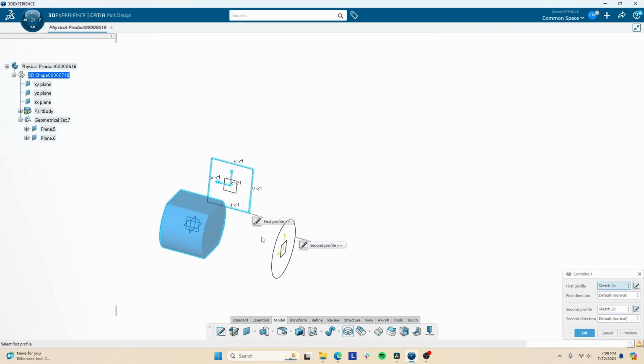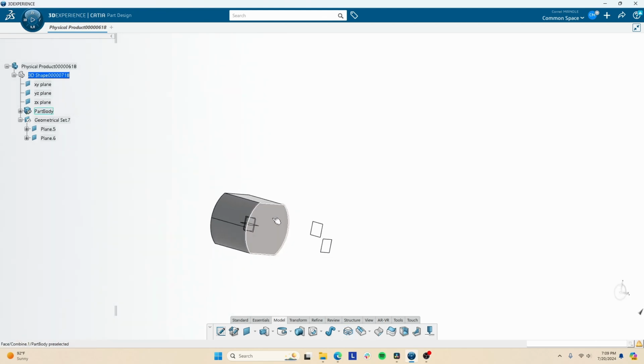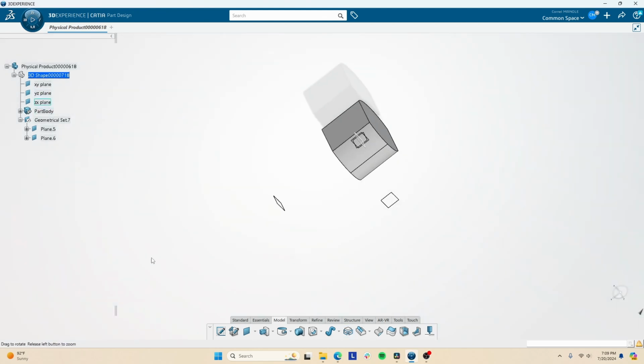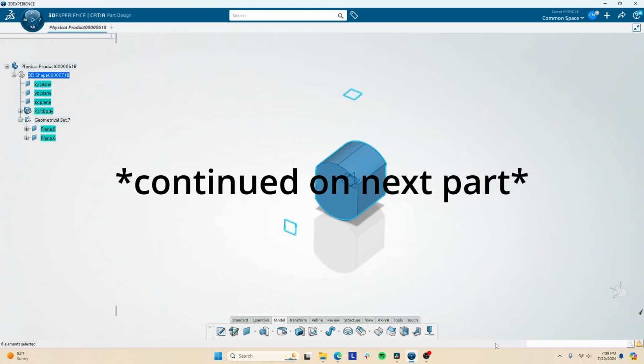Then it will create a solid that is the result of the projections of the sketches, with the projection directions being by default normal to the base plane of the sketch. If you wanted a different direction, you could also create your own lines and axes and specify the projection directions. Okay. All right, let's go back. We could do a multi-section solid. Let me delete this and set that up for you.